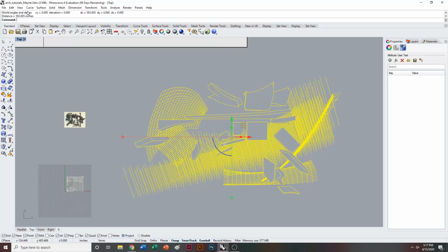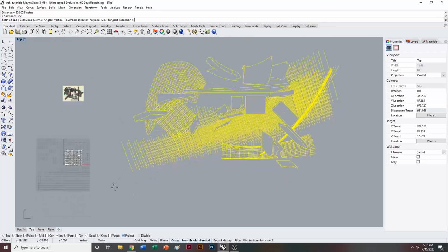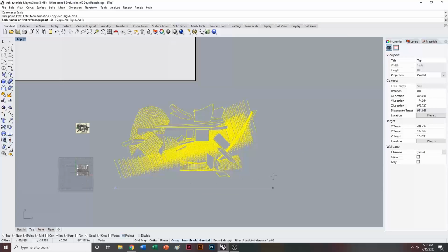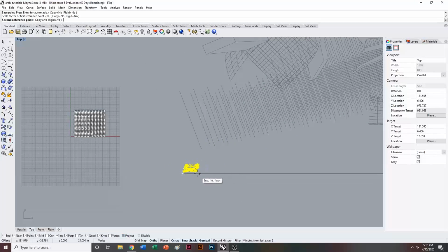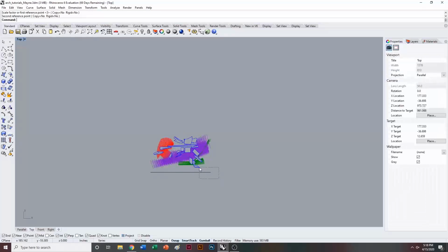Ideally, the images that you produce for Garrett and I will be between 12 by 12 and 24 by 24. So I can do the conversion based on this 593 inches. I'm going to type in line and basically just say like 2 feet, which is the apostrophe key on your keyboard, and hit enter. Then I'm going to type in scale and bring everything ballpark down to about that size. So that was our line, so I think something like that will be good.